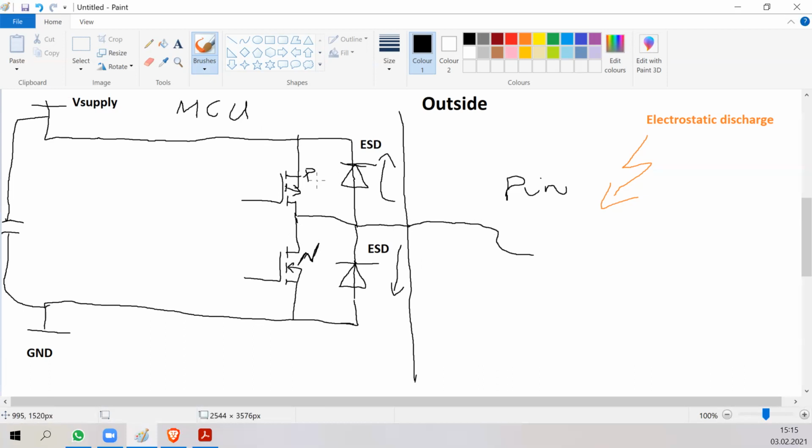And as I mentioned, these EFM32 microcontrollers also have a current limiter, but many microcontrollers don't have that feature, so I will not draw it in this picture. Also, there's a small series resistance, also for protection against short circuits and electrostatic discharge. These MOSFETs are used for output, but if you want to use it as an input, then both of these MOSFETs are shut off. And then